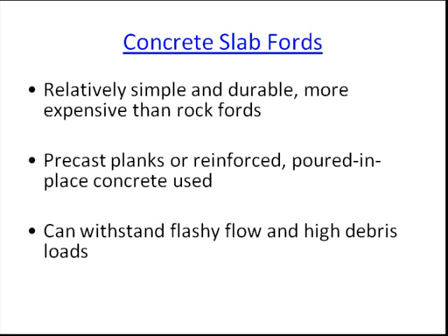Another form of improved ford involves the use of concrete as precast planks or reinforced poured-in-place slabs across the stream. They can be relatively simple, but also more expensive than articulated mats or rock-hardened fords. They're durable and well-suited for systems with flashy runoff and high debris loads.